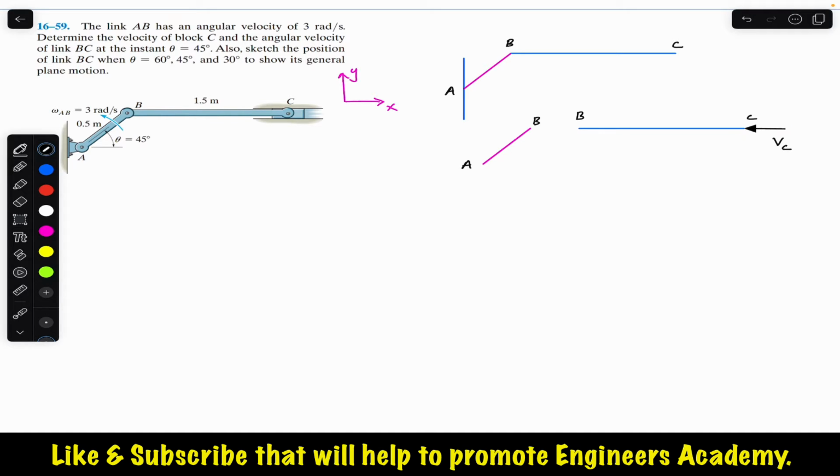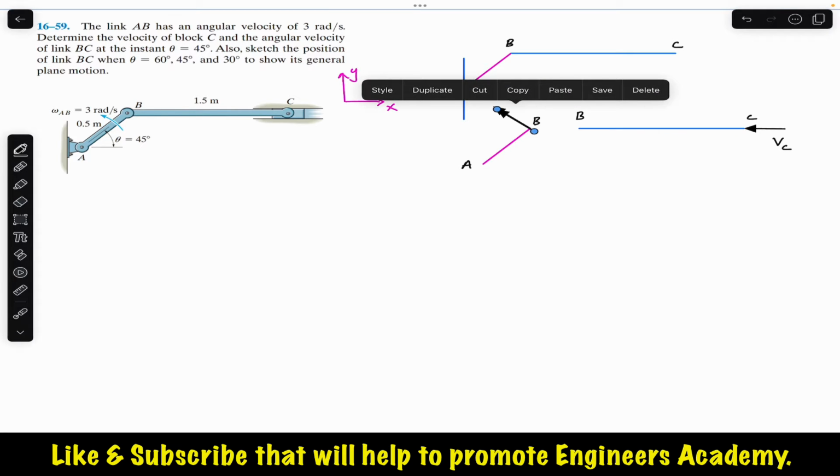This is VC. And similarly, as we know, this point B is moving only in a circular path since it is revolving around this fixed point A. So its velocity VB will be tangent to this AB link, right? So VB will be in this direction. We can show the VB velocity vector here at link AB, and similarly we can show the same velocity here as well.